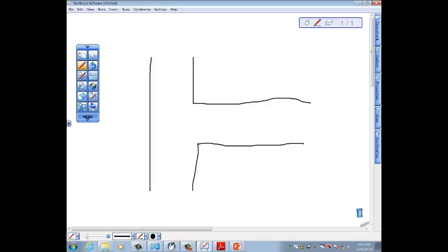And then if you're looking on page 551, you can see how the steel is formed. So, 10-inch wide by 18-inch deep beam with 2 number 9 top bars and 2 number 8 bottom bars.